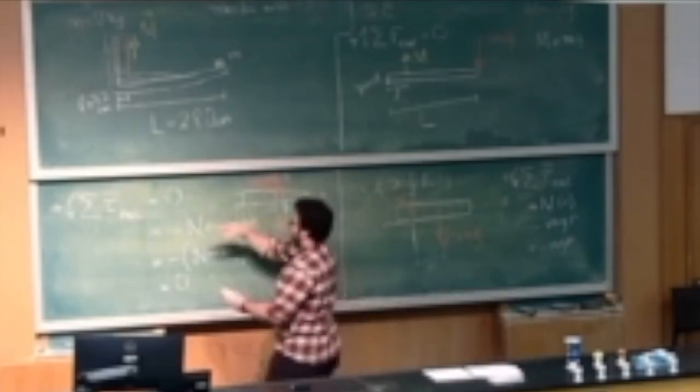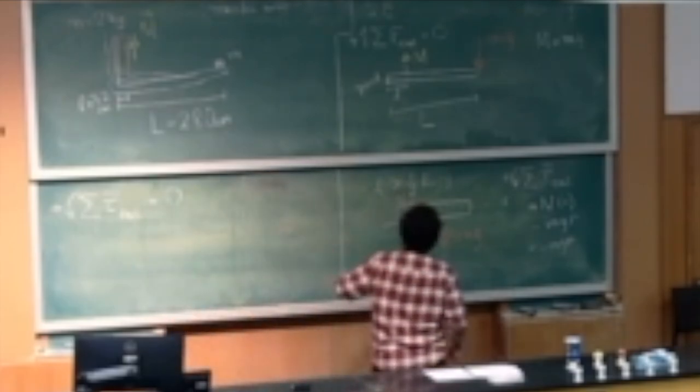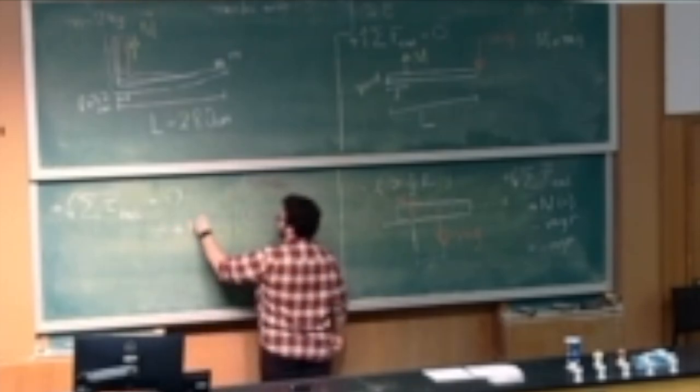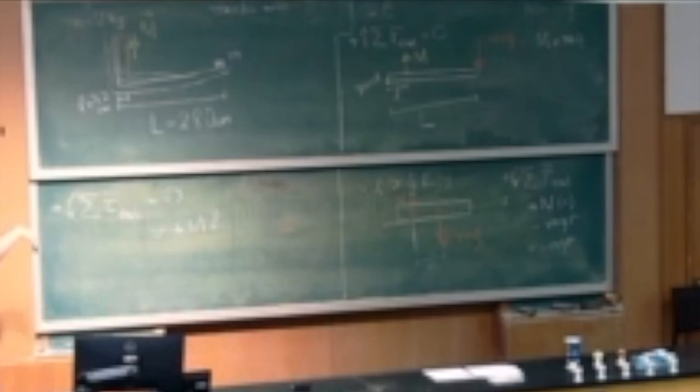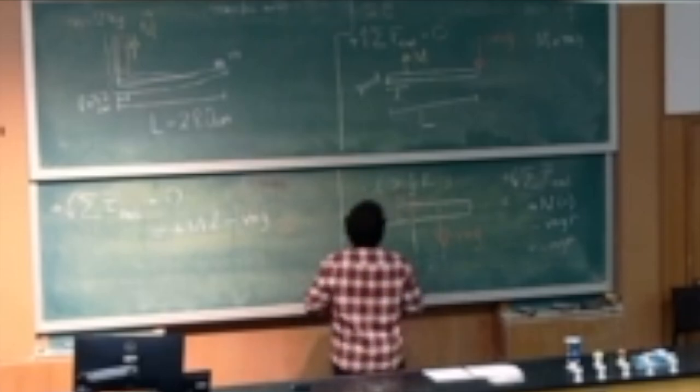Okay, now, I'm just going to keep this and remove everything else. So we now try to understand the torques. And that's our pivot point. And again, I will always assume the counterclockwise direction to be positive. So let us write down the total external torque or moment for this structure. We have uppercase M, the muscle force, trying to create a torque in the counterclockwise direction, right, with a moment arm of lowercase l. So it is positive in our convention. And we have the weight, mg, that is trying to rotate the arm in the clockwise direction, so it will have a negative contribution to this expression. And the moment arm is equal to L.